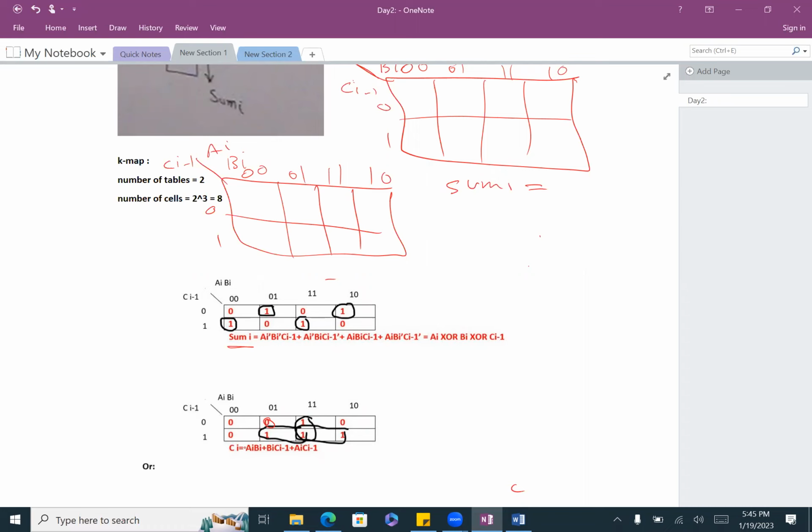All right. So now that's our table. We did 0, 1, 0, 1, 1, 0, 1, 0. Now let's combine the ones together. Can we combine any ones into groups of 2, 4, or 8? We cannot, so when we write the equation, it's going to be separate for each one of them.